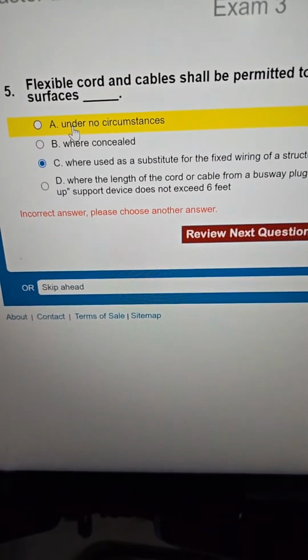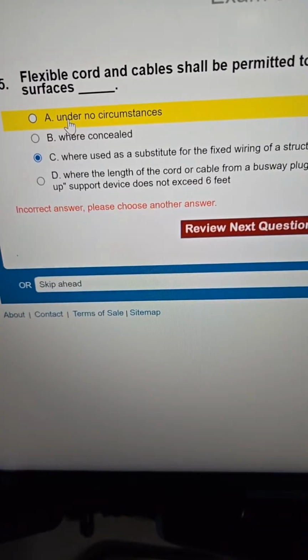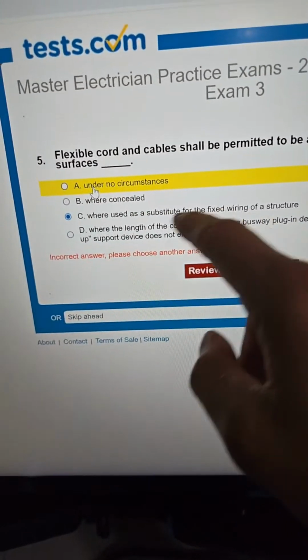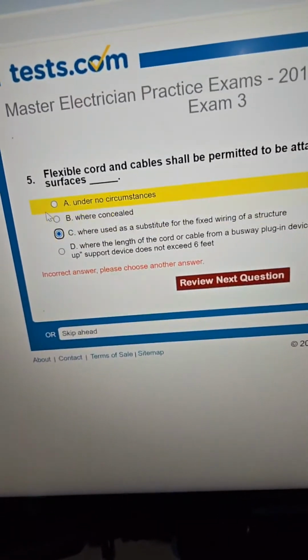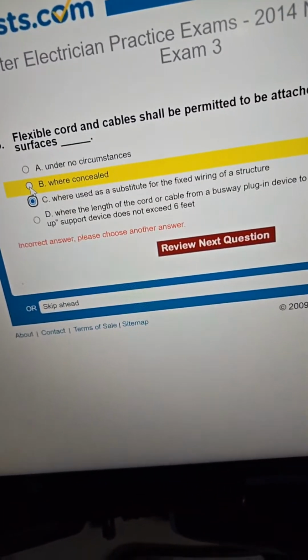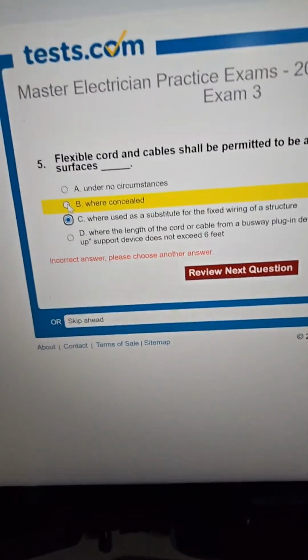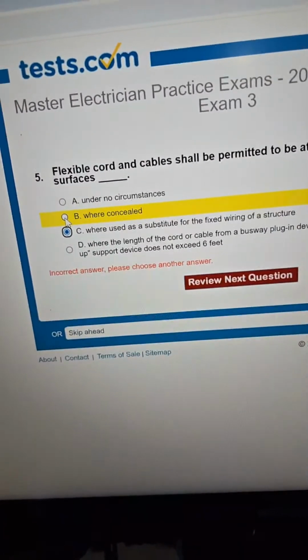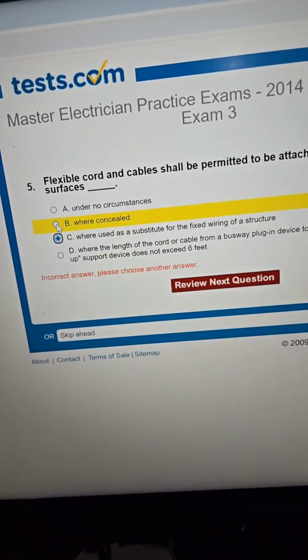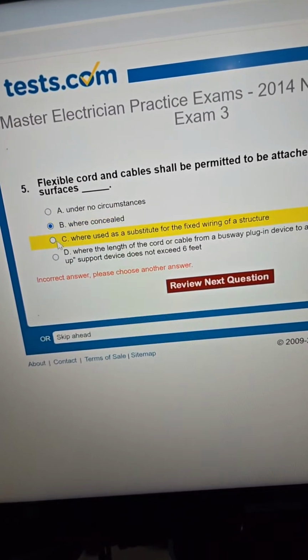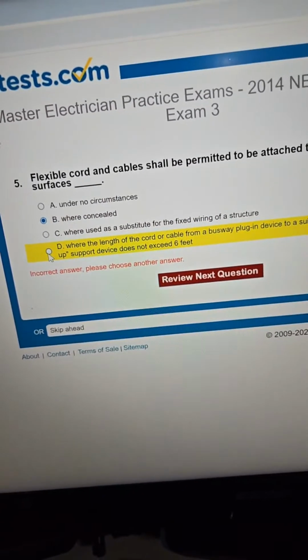You also can't conceal them either. But you also can't use them for accessories. You're not allowed to have premise wiring for cords and cables either, but you definitely can't run them through a wall, so it's probably concealed. This is why you can't have mirror lights with receptacles behind them. So this is probably the answer now. It's still not the freaking answer.